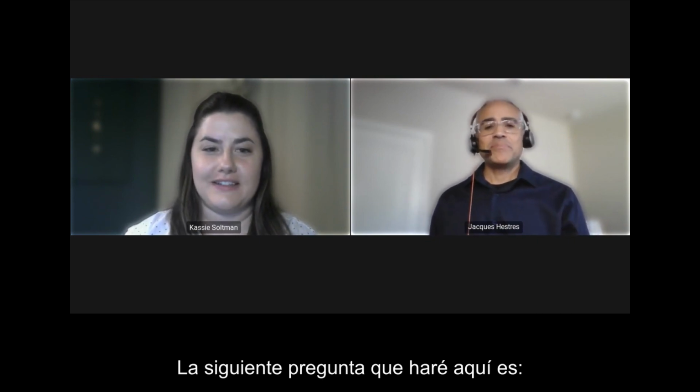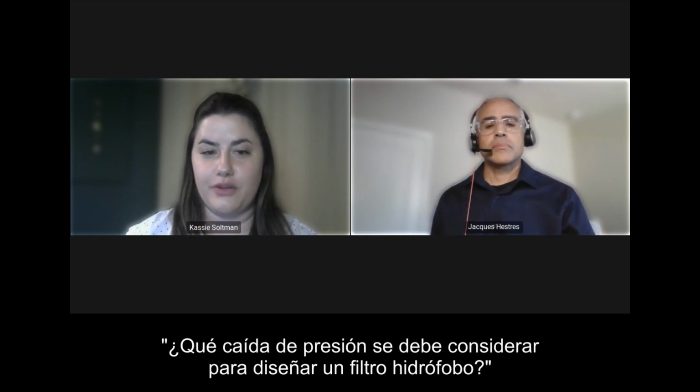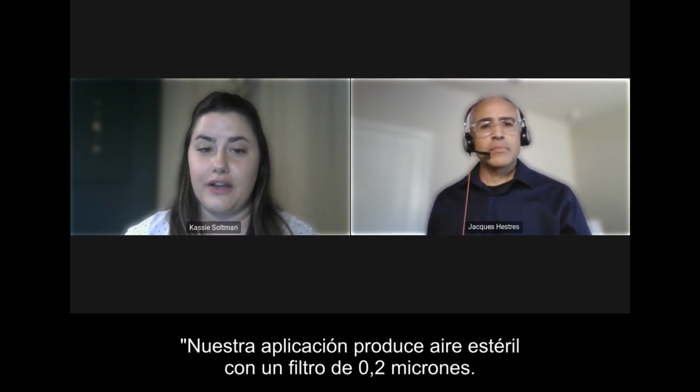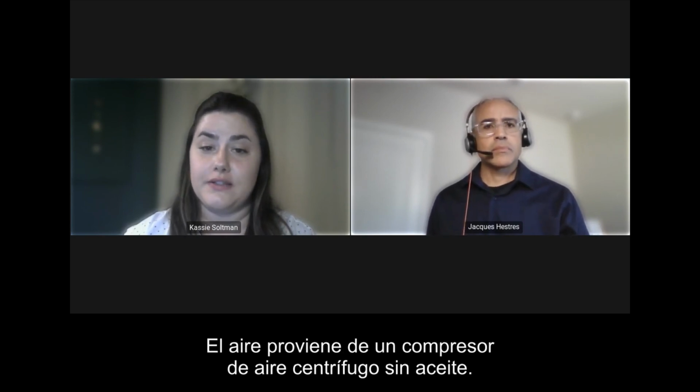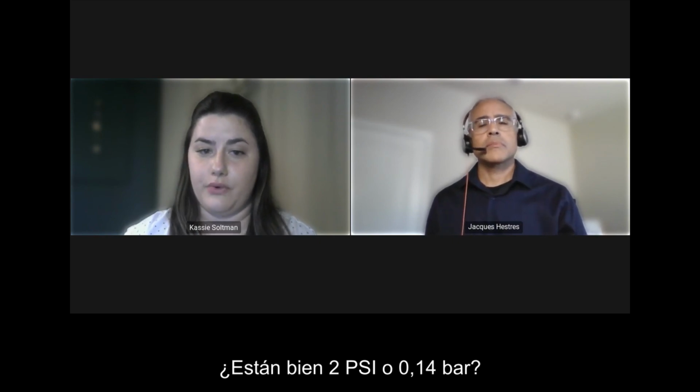I think it does. Our next question says, what pressure drop should be considered to design a hydrophobic filter? It's a two-parter. Our application is to produce sterile air with a 0.2 micron filter. Air is from an oil-free centrifugal air compressor at 2 psi or 0.14 bar.